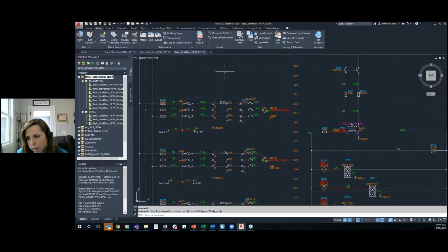Okay, Brandon, let's see. Also adding the command to the... oh wait, let's go back up. I think we skipped over your initial question. Insert terminal schematic list will show a dash or an X, but does not show an O, a mismatch of information as detected, like the wire number has changed on the schematic, so the terminal needs to be updated.